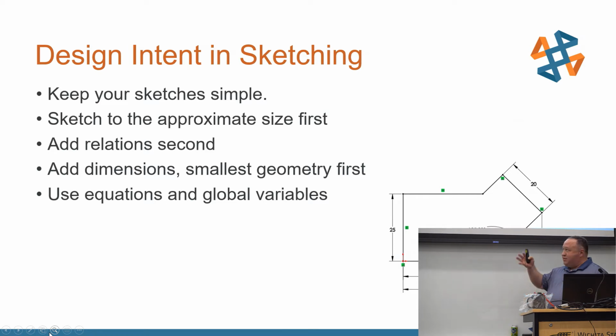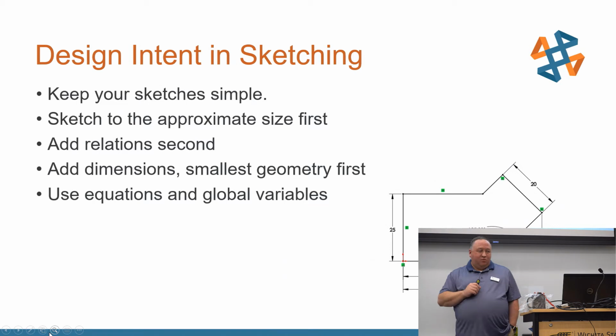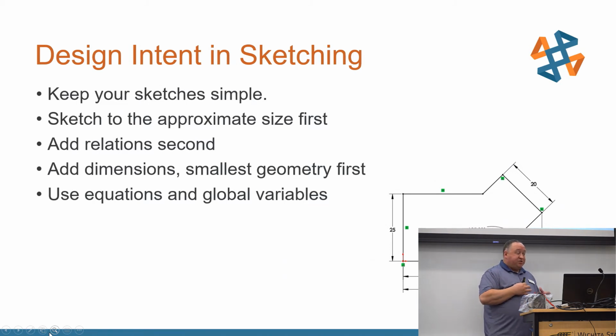So again, just kind of a summary of design intent in the sketching mode. We find that you should try to keep your sketches simple. Simple sketches are easier to edit, and take less time to produce or to consume inside of SolidWorks. It rebuilds faster. The least amount of entities you have, the faster it will rebuild.